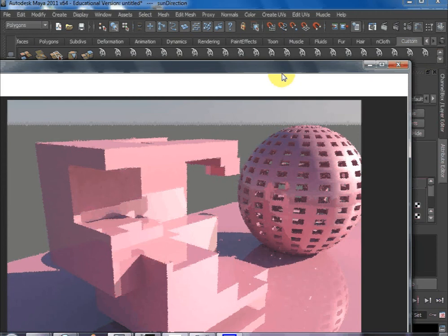So we got this in Mental Ray. If you like other styles, like software rendering rather than Mental Ray, that is okay. You need to watch my other tutorials. If you don't want to use Mental Ray as a rendering engine, you can set up other lights like a spotlight. You can set up the point light. You can have other manipulations. Not much difference.